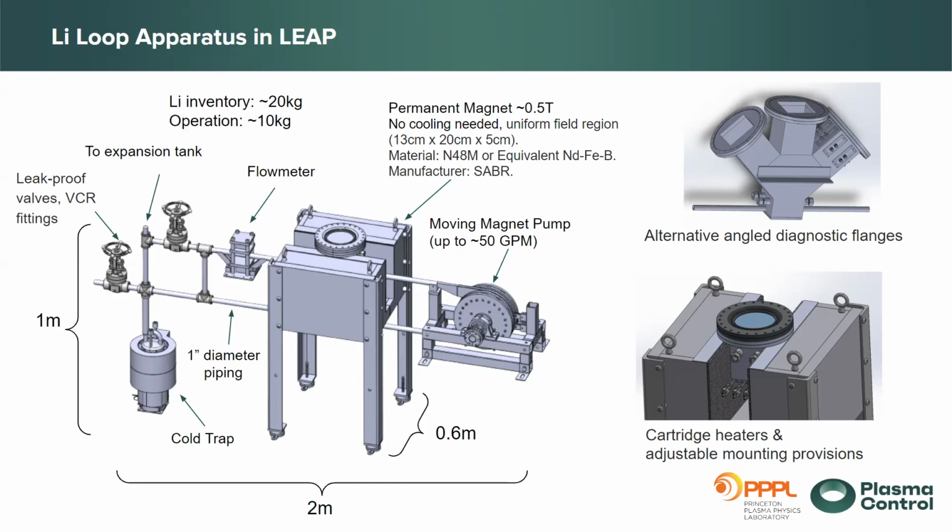Yeah, thank you. We have considered this. The whole idea of this is the secondary confinement, in case of catastrophic failure of the first layer. If you have molten lithium coming out of these pipelines, the whole box is made of stainless steel with a definitive depth at the bottom, which has enough thermal mass to stop lithium from reacting further. It will cool down and solidify the lithium.